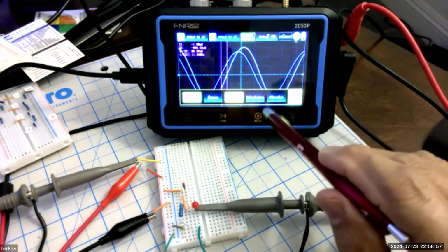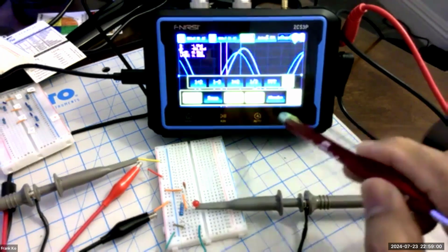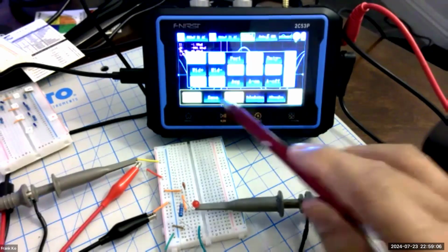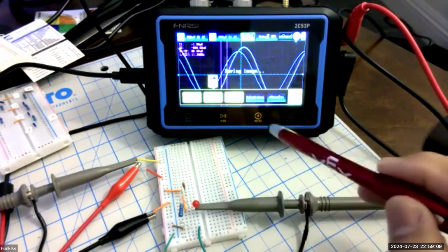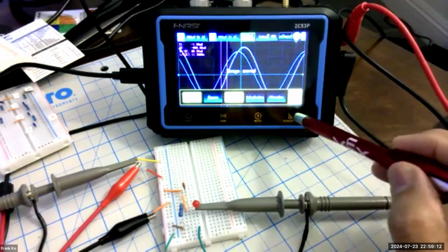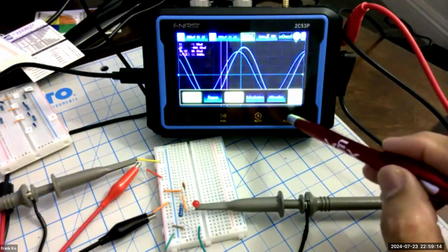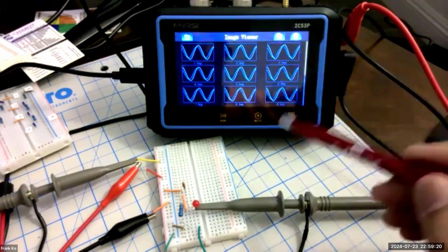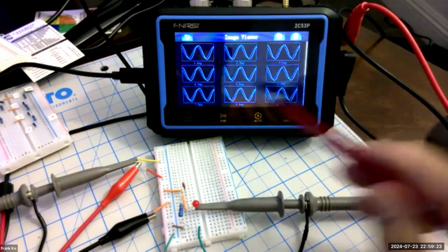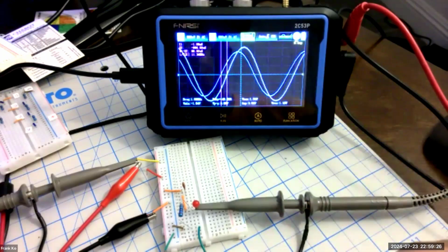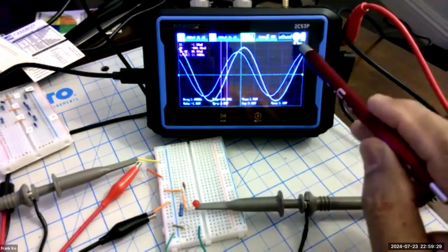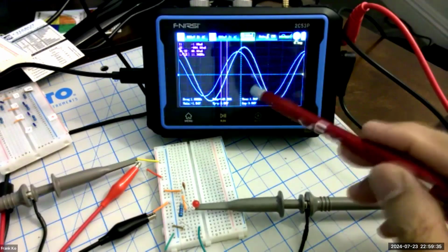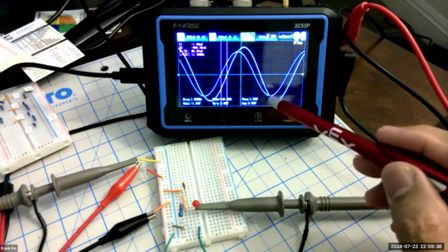You can decide also in the calculation what type of information you want in the measurements. And then you can also save these images to a built-in memory card so you can call up the waveforms at a later date. So I can do this and go to here, image, and I've already saved like 12 different screenshots that I can recall at a push of a button right there. This is one of the ones that I've saved. In fact, this is image number 6. So it's not the same as what you saw 3 seconds ago, but it's almost identical because this is just a fascinating wave shape to display.